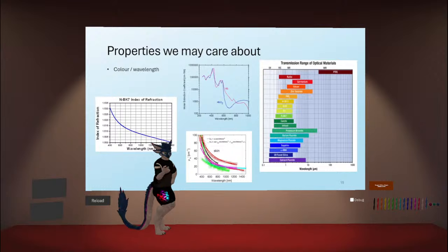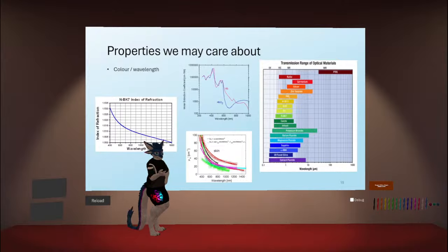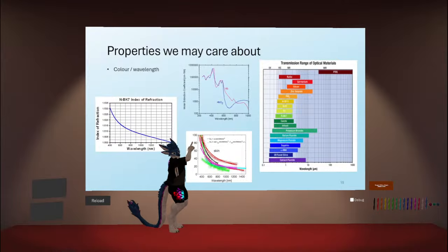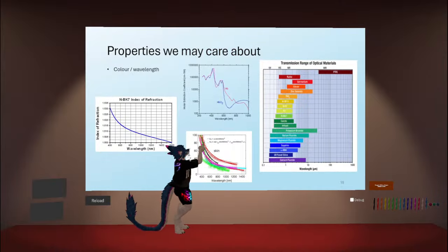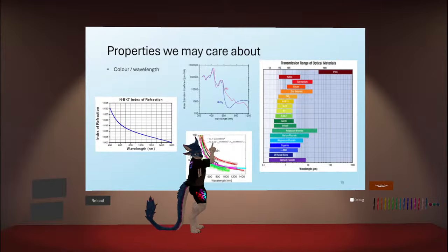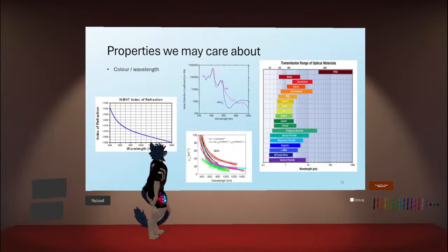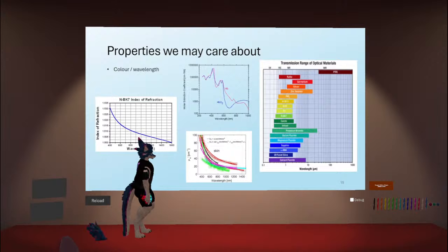I don't know if y'all remember the phase with smartphones from a couple years ago, where you had that little sensor you could put your finger on, and it would shine a bright red light into there, and it could tell you your blood oxygen saturation. It's just using this curve right here. It's just looking at the amount of light that gets scattered back off two LEDs, and basically solving a very simple linear problem to get back at the relative oxygenation.